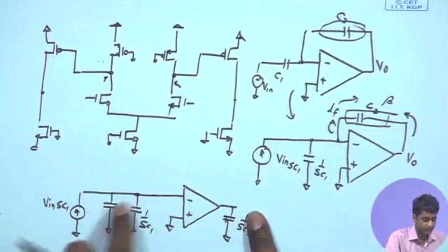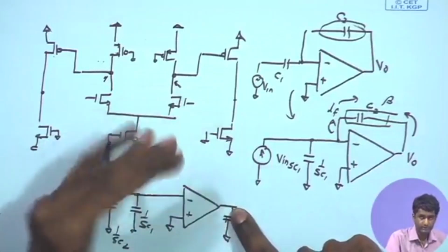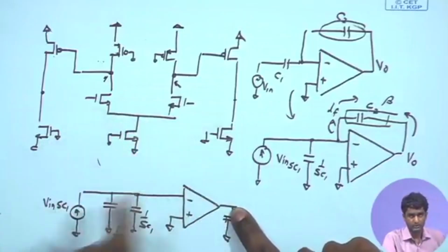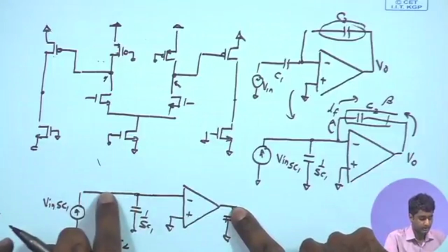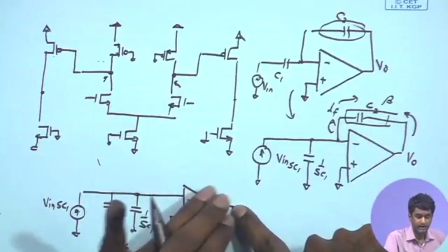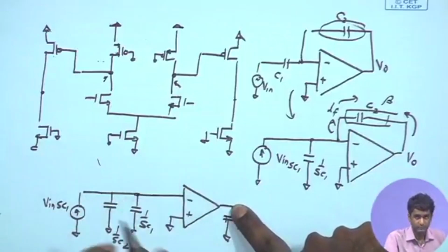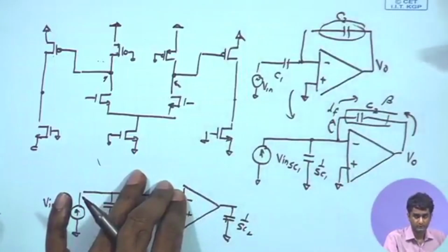For that, we first need to figure out the output voltage over here, and from there find out the feedback current. That is the overall operation, right. So, A, the open loop gain, is basically the current to voltage gain multiplied by the feedback factor, which is the voltage to current conversion factor obtained by this feedback network, that is known to us.